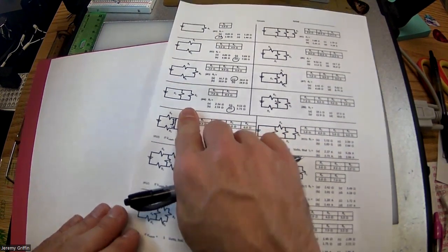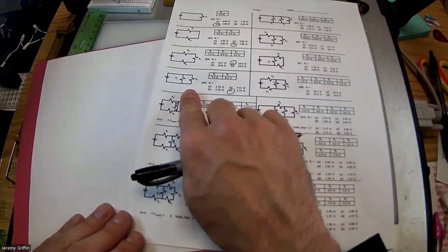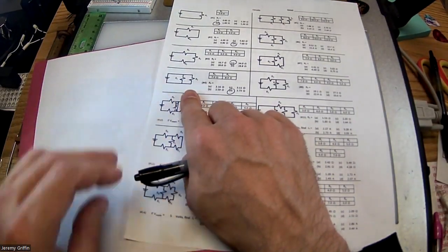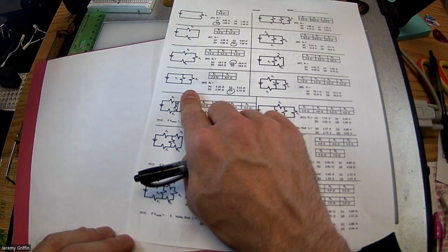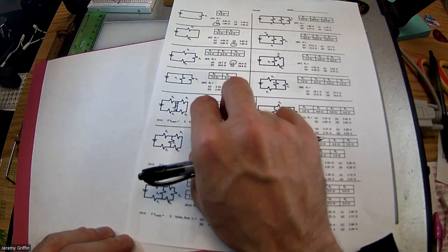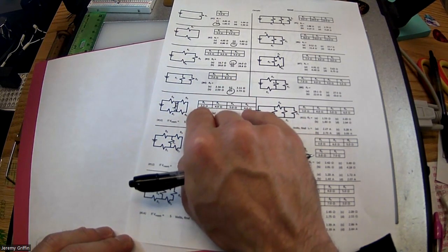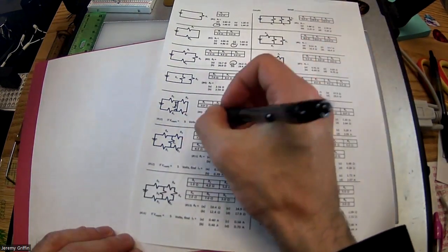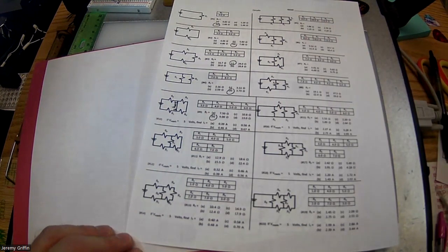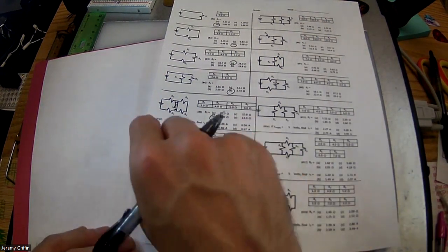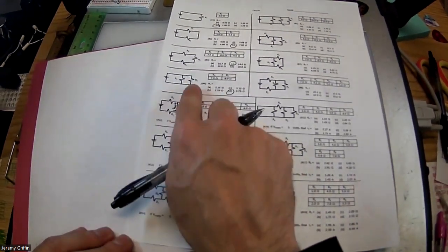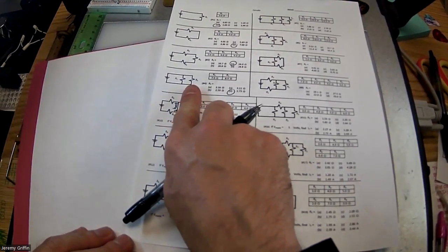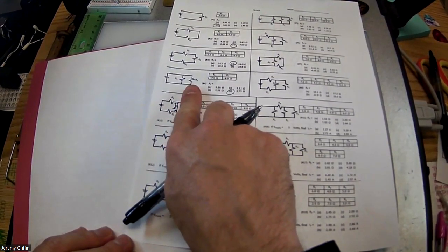Hey, doesn't that look exactly like number 2? Aren't those 2 resistors, R1 and R4, in series with each other now? Okay, so I can just add these two guys together in series. So I've got 3 ohms and 6 ohms makes 9 ohms. Okay. So just add R1 and R4 because R1 and R4 are just in series with each other. Right?